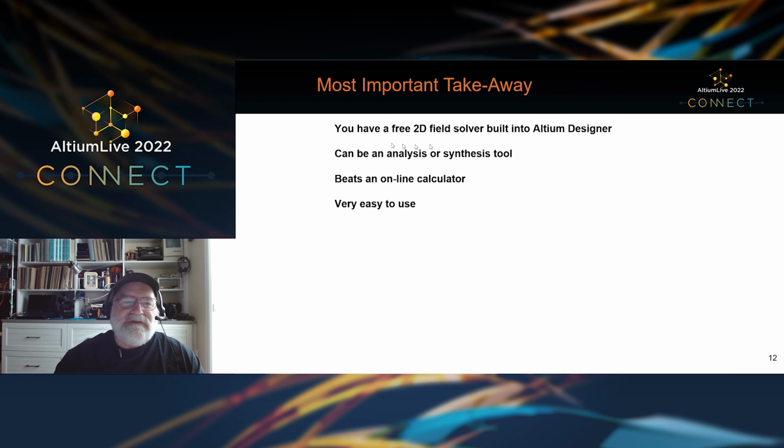I wanted to introduce you to the 2D field solver that's built into Altium Designer. Now you have access to it, and you see how easy it is to use. You can use it for analysis or synthesis. It's better than any online calculator you're going to find because you can do the analysis of the second order factors, mixed dielectrics, the impact of the solder mask, the impact of the etch back. In the Stackup, you can have multiple dielectric layers with prepreg and core, each with dielectric constants. And of course, you get that information from your fab vendor based on what Stackup they're going to use. And we saw that it's really easy to use.